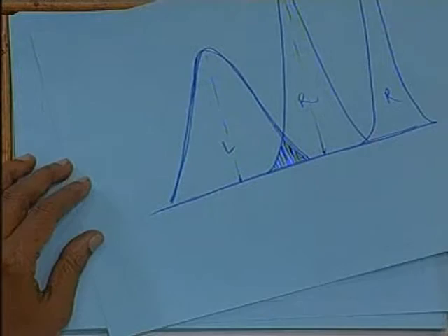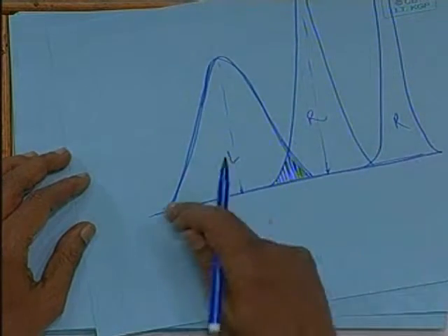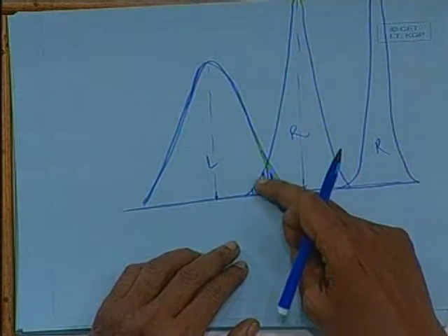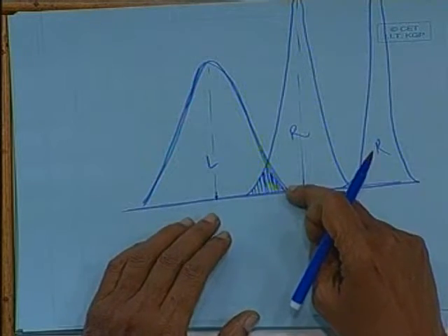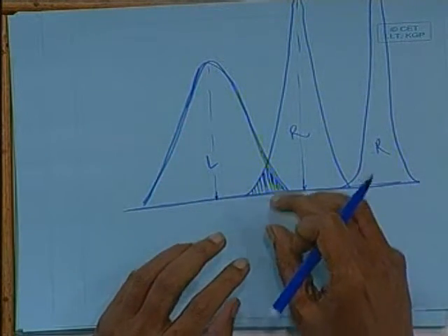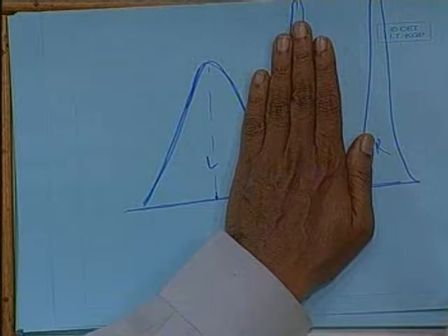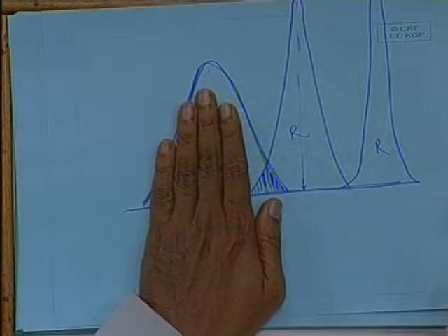Level 3 on the other hand is a more theoretical approach where we model these curves exactly, and if they can be mathematically modeled, it is possible to find the area enclosed between the intersected portion, and that becomes our failure area. Based on that we can say that this structure which is likely to experience this load and which is likely to have a resistance of this nature will have a reliability index so much, which will be 1 minus the failure index. But this is very difficult.